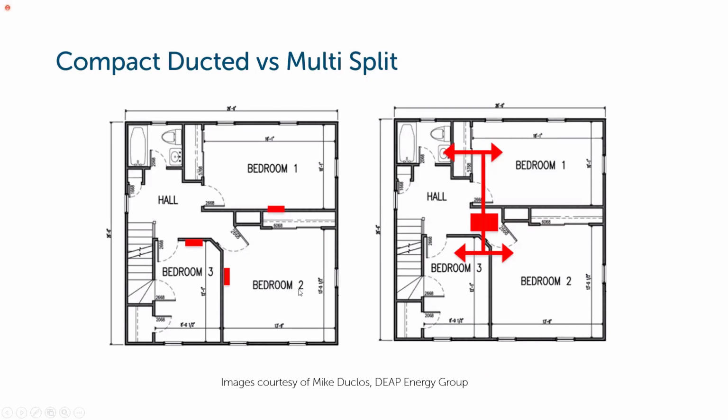So this is, again, reinforcing the idea here: a multi-zone single condenser unit with 3 mini split heads trying to condition 3 different bedrooms, versus the philosophy of using a central air handler in the hallway that's feeding the individual rooms off of one head. Better load control with this system than with this system. Are there any questions?